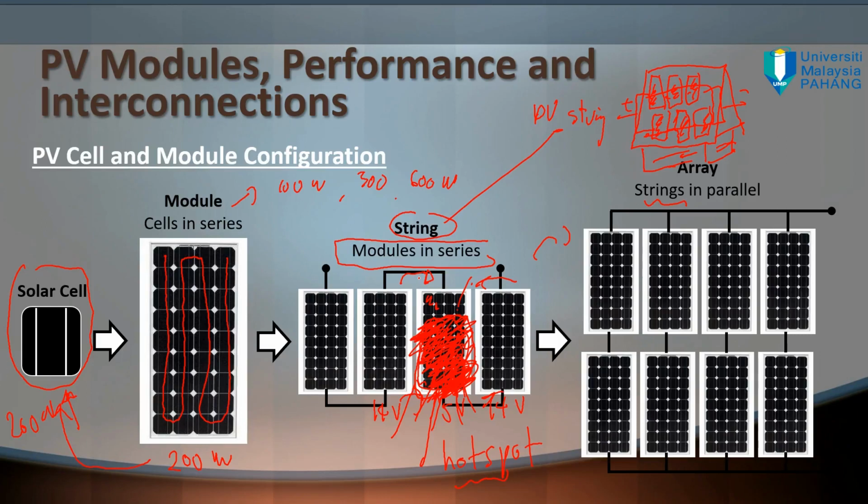Usually they check through the inverter. If there is an abnormality in the output power from the value shown in the inverter, then they start to investigate or clean the modules. By default, if there's no problem, they just leave it. If there's a problem, then they try to investigate or do the cleaning. Sometimes they already have a schedule for the cleaning.